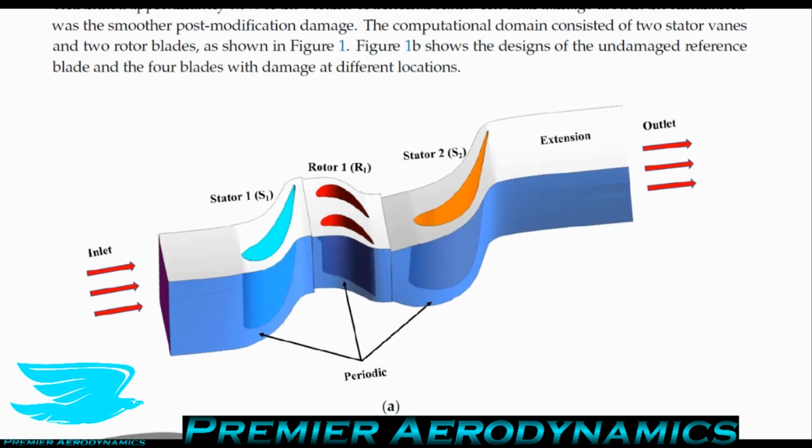pressure as the ambient. The reason why is because that will mean that you've expanded the flow enough and you've extracted as much energy as you can. Now, if you don't do that, then it's called underexpanded because you haven't expanded it enough. That means that the pressure coming out is higher than the ambient, and then the wake, or the jet coming out, will expand as you come out.